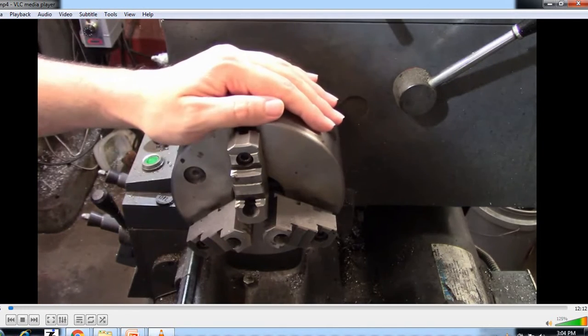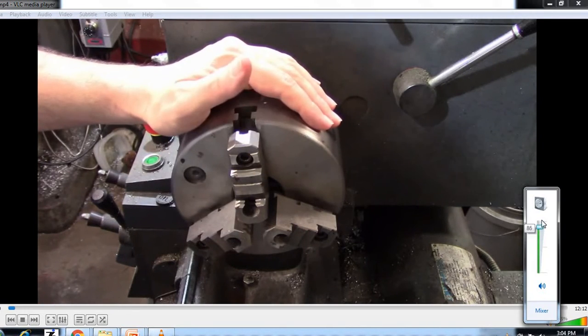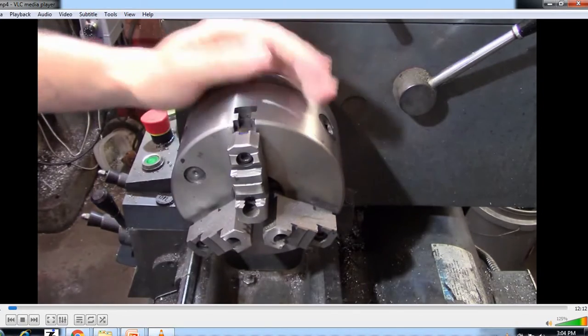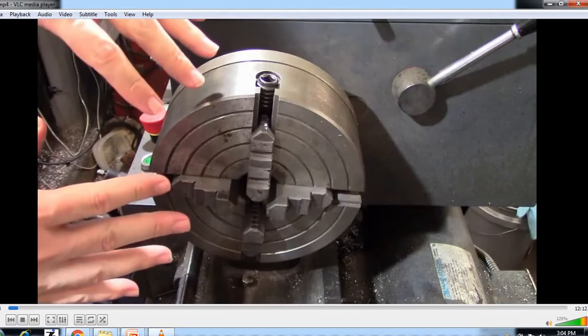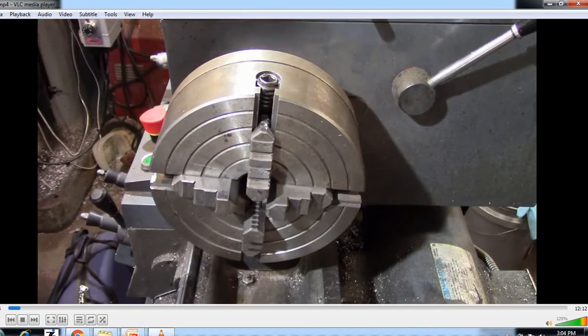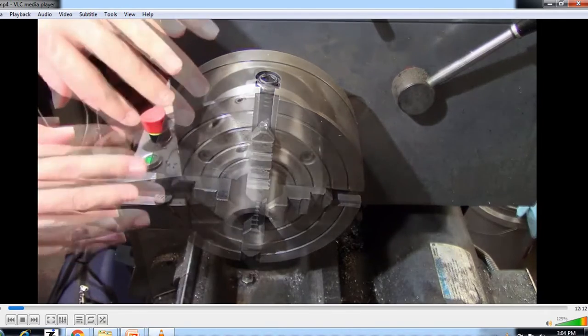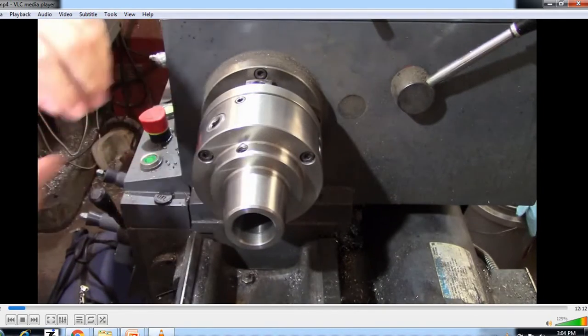The most commonly used work-holding device for the lathe is the chuck. Chucks come in two varieties, universal and independent, and can have 2, 3, 4, or 6 jaws. Collets are also very commonly used for their speed and accuracy.